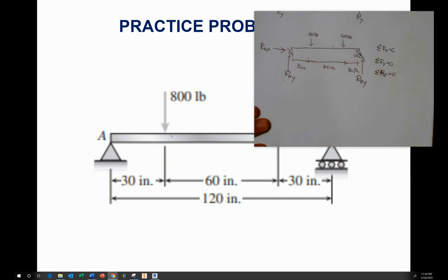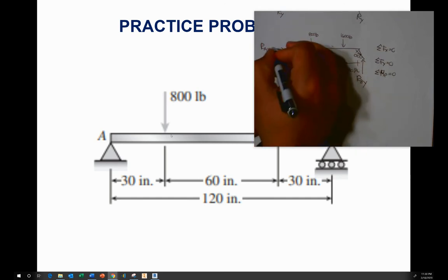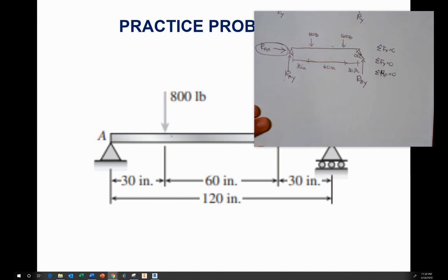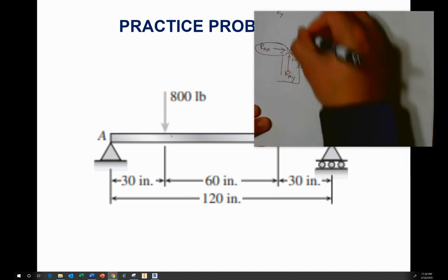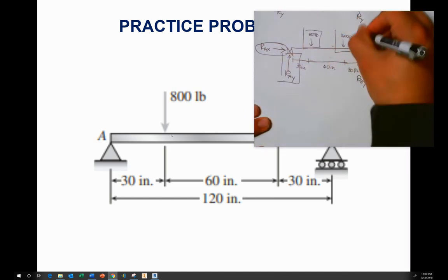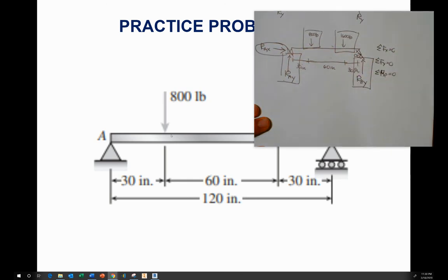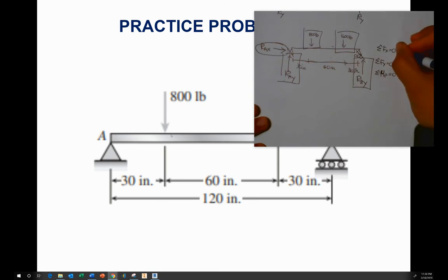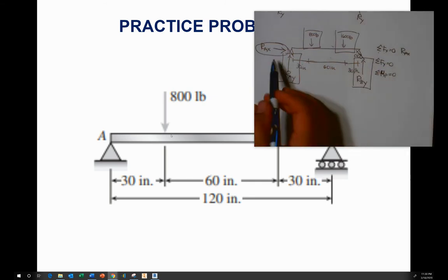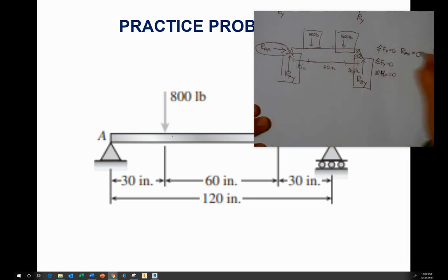All right, now we go ahead and just, well, this is a free body diagram. I always like to suggest to people, I always circle my X forces. I always box my Y's. All right, well, this makes it pretty straightforward. It tells me that Rax, so again, sum of the forces in the X equals 0. There's only one, so we know Rax is going to equal 0, which technically I said earlier already.